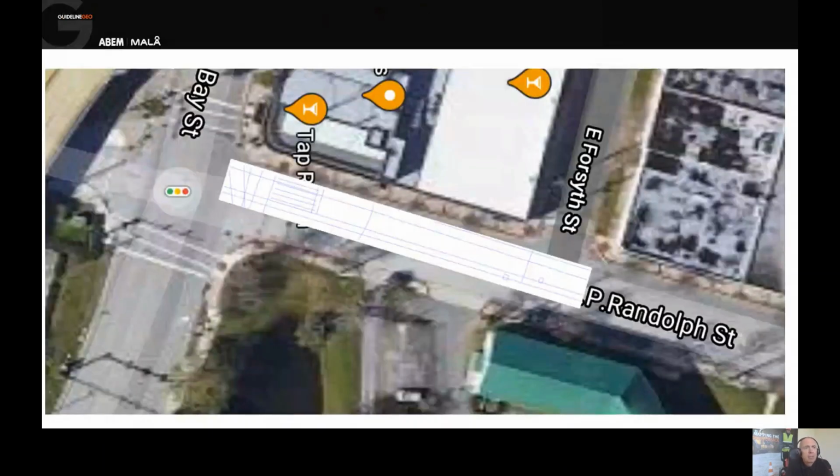And we created this map at the end of the day. And we've got some things down here from the traffic lights. These are the sensors, and then we can see the utilities crossing and the utilities running down the actual street itself. So this really gives us a good indication of the effectiveness of the GPR, and moving forward, it was recommended that GPR would be the way forward, just for that initial mapping out of the utilities and the position of the utilities itself. So a very quick and efficient way in this situation.